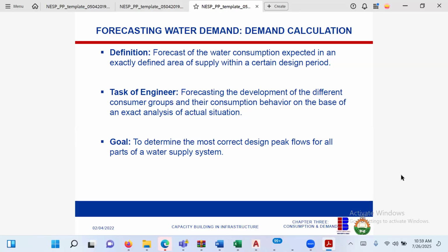You need to say, I'm designing for 30 years, or 50 years, or the next 20 years, or the next 100 years. 100 years is too much. Forget about it. And besides, who told you that in 100 years' time, development would not have overstretched your design? So typically, people design for 25 years or 50 years. But remember, the factor of safety is something you need to be careful with, because the higher the safety factor, the higher your values, and the higher your cost.